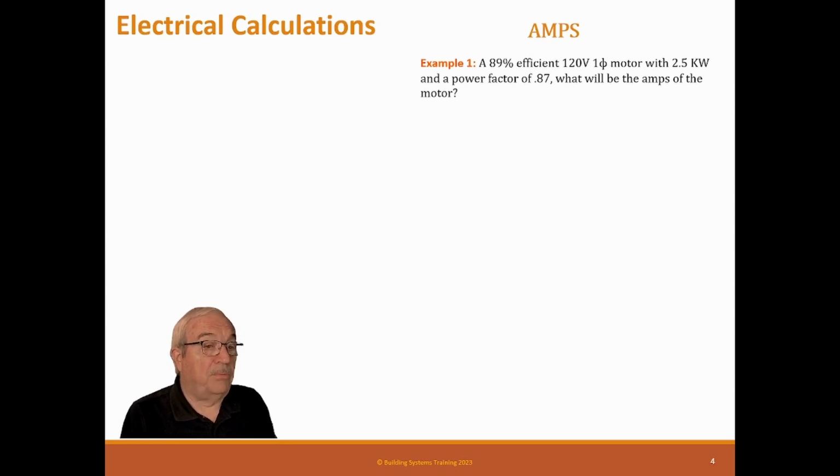Now, if it's 0.89, that's a really good power factor. Power factor 1 would be perfect, right? But as long as you've got a motor in the circuit, you'll never get 1, because motors, actually induction motors, kind of screw up power factor a little bit. And so do other devices, but mainly motors. So basically, if you're guessing power factor, guess somewhere between 0.86 and 0.89. You'll be safe. 0.89 is a nice safe number. That's a good power factor, right?